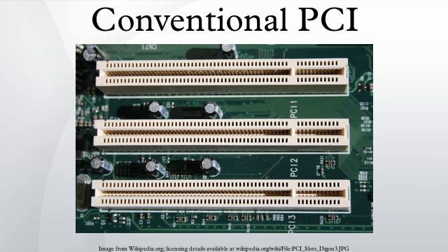Data phases: after the address phase comes a burst of one or more data phases. In all cases, the initiator drives active low byte select signals on the CBE[3:0] lines, but the data on the AD[31:0] may be driven by the initiator or target. During data phases, the CBE[3:0] lines are interpreted as active low byte enables. In case of a write, the asserted signals indicate which of the 4 bytes on the AD bus are to be written to the addressed location. In the case of a read, they indicate which bytes the initiator is interested in.